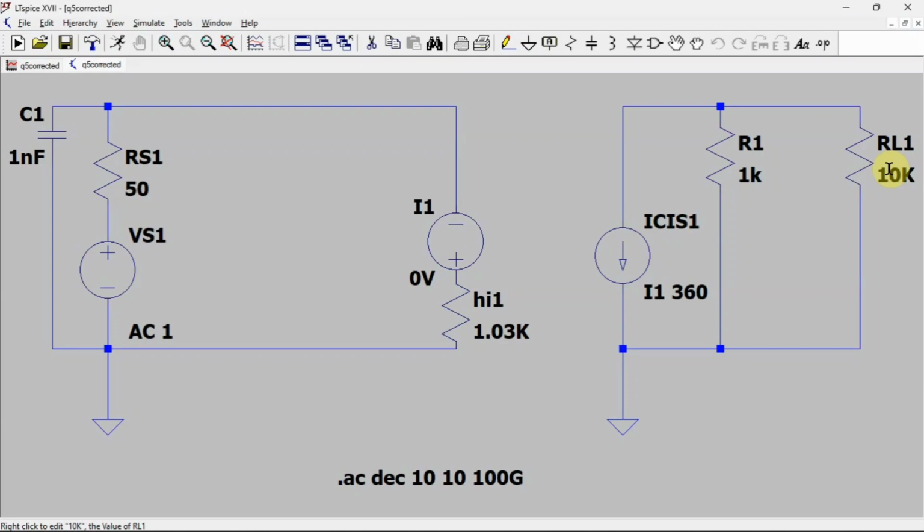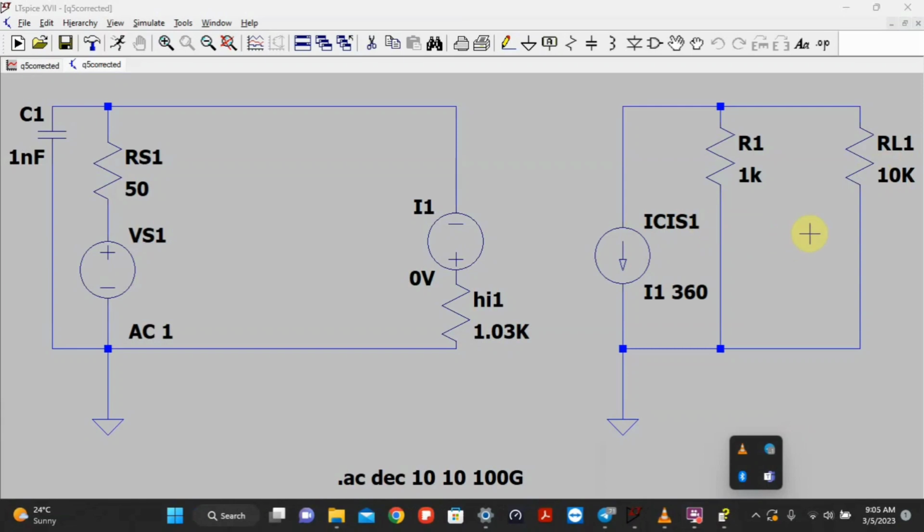There are usually two cases of step parameter. The first case is directly assigning particular values. This is not only useful for resistors, it can be used for capacitors, anything. You can make anything a parameter and change its value. Let's see how to do this for the resistor.